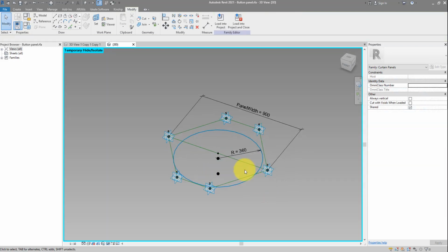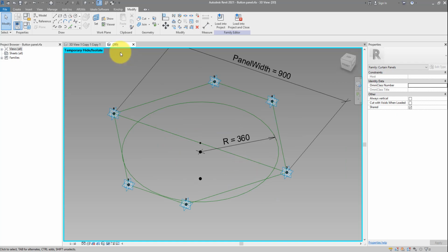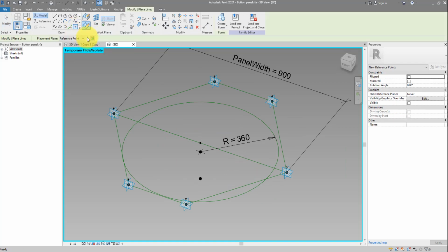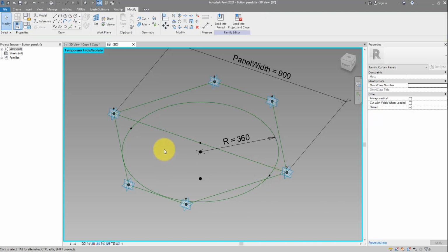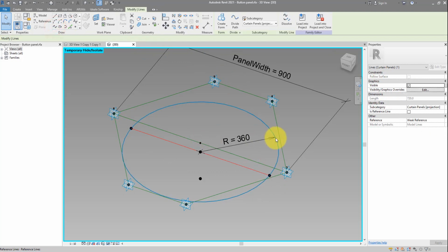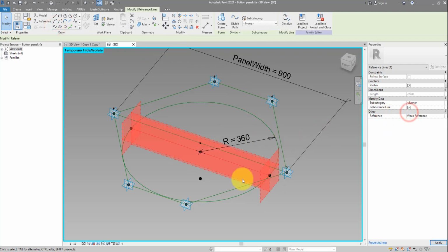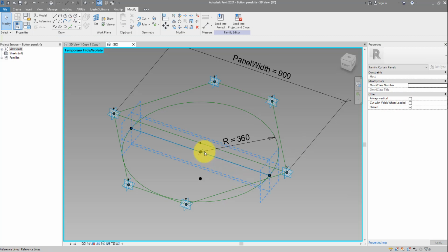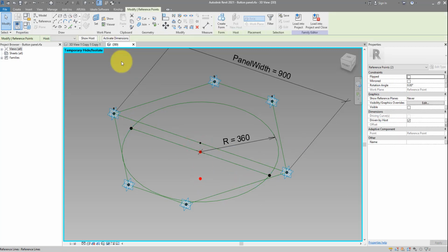Next thing to do is to create the axis of our panel. Let's go to here again, make another point, this time on the face, and drop it right there. You will see a diamond snap icon lighting up, and that means we're snapping to the quadrant of the circle. So get this first quadrant, and then to the other side, get the other quadrant point here as well. I can now connect those 2 points using a spline, which should also be a reference line. Next logical thing to do is to connect those 2 points below there, using the same method.